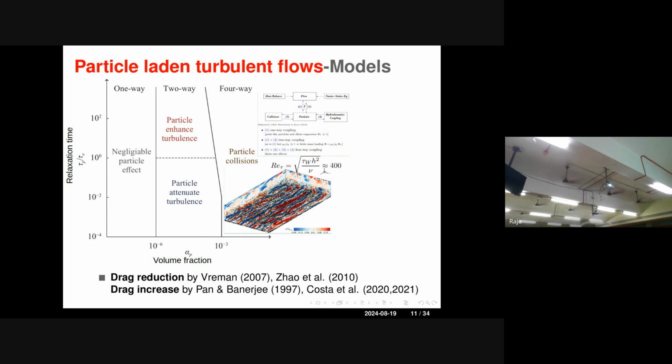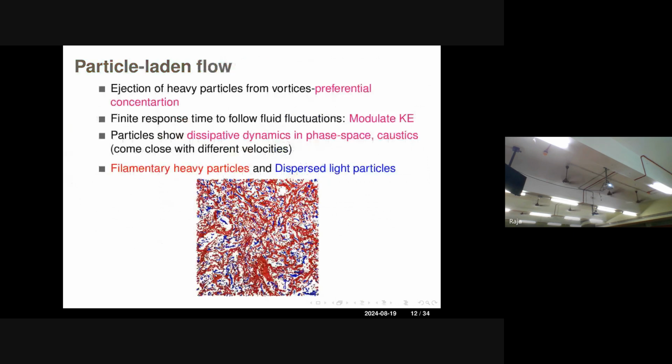At certain locations or in certain problems, people reported that drag was tremendously reduced by having these particles. Some studies say that drag tremendously increased in this kind of system. So there are always these arguments about in which cases drag enormously increases, so choking or an increase in pressure gradients develops, or where exactly drag really reduces. Usually, these particles behave in a very crazy way.